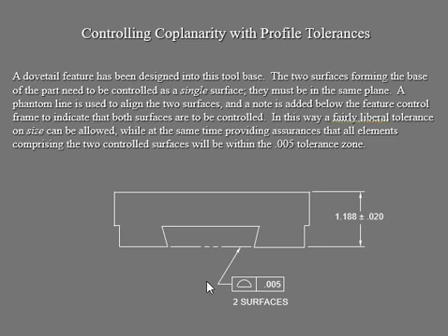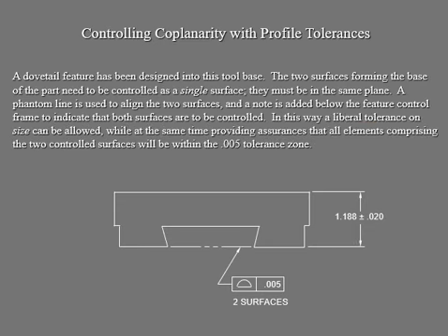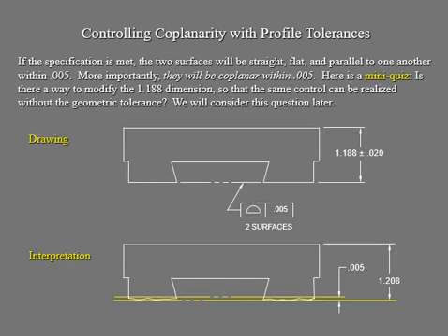So we'll get into the frame right there. Your frame is here with 2 surfaces. Your control tolerance is right there for this profile. We can identify it with this profile symbol right there. And of course, this is your size and the tolerance. Again, we're dealing with 2 surfaces, but they can be controlled as a single surface, because it's a coplanar surface anyway. Here, pointing at this surface, 2 surfaces, but treating them as a coplanar surface because they're sharing it.